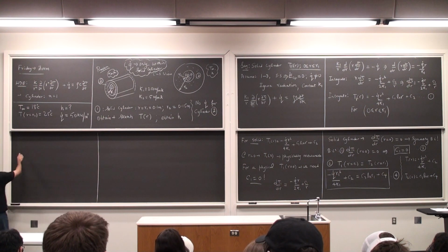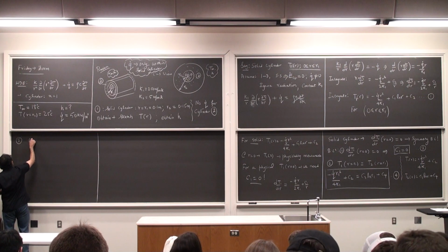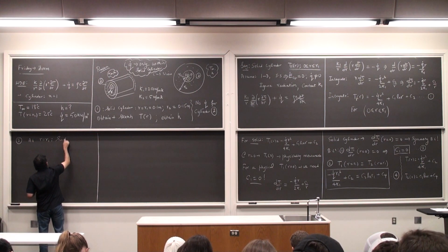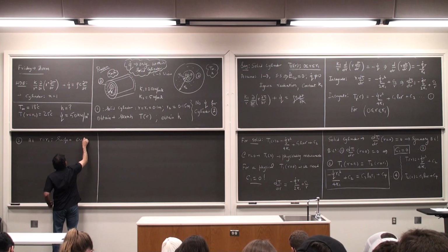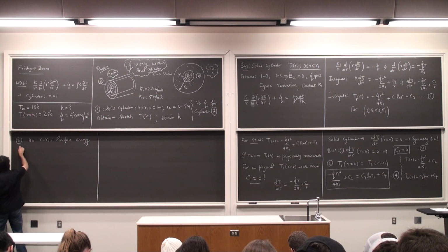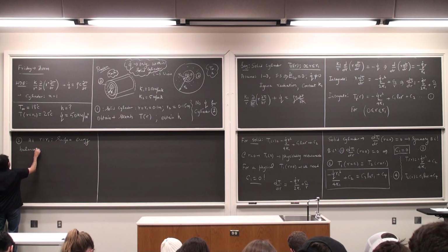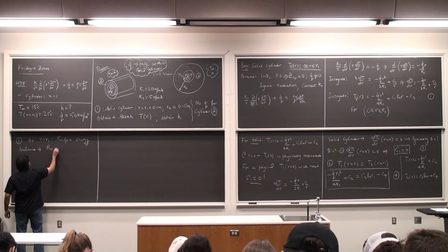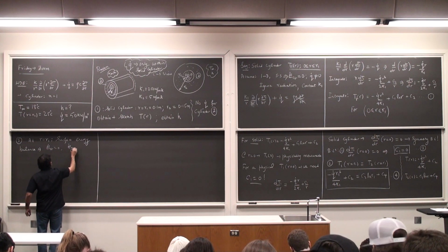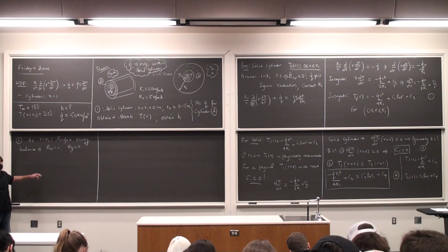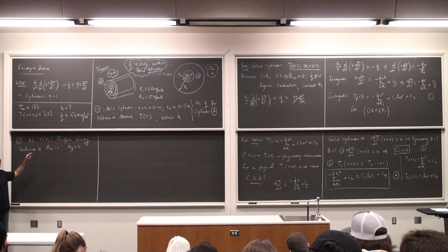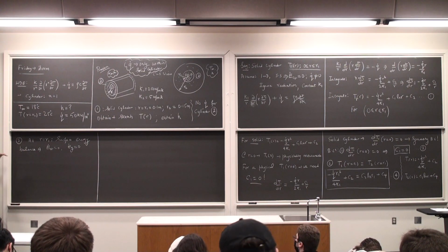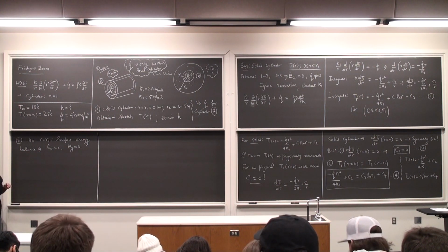Okay, so at R is equal to R1, surface energy balance, which implies E dot stored is 0, E dot G is 0. This is irrespective of the fact that there is energy generation in the solid cylinder. That's something to keep in mind. Okay, if you're doing a surface energy balance, energy in is equal to energy out. That's it.